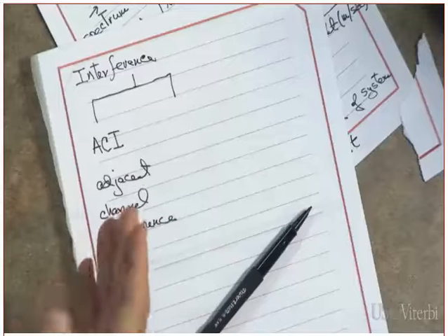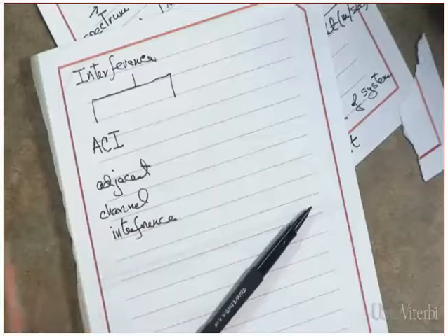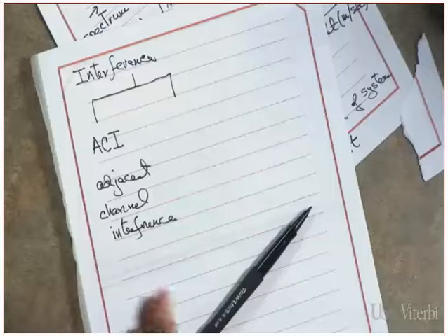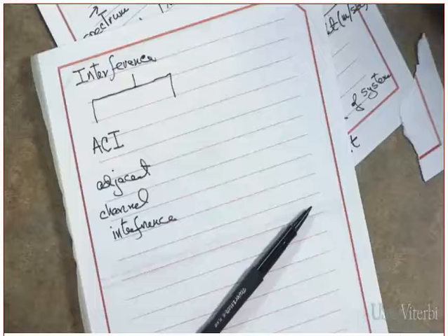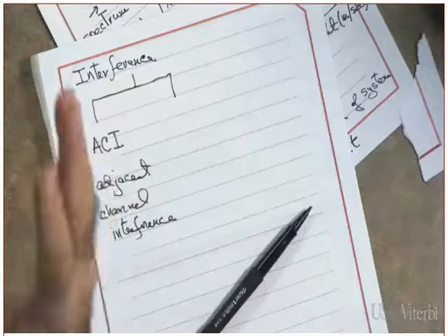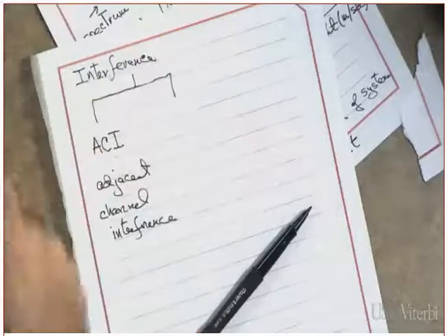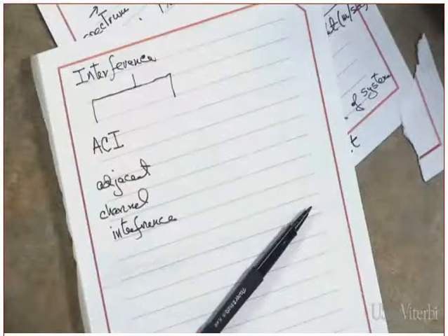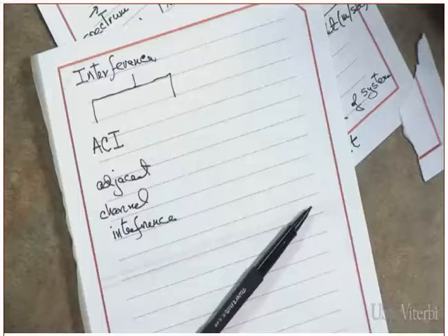Now you do understand that one of the most important parts of designing an RF transmitter is to make sure that your emission, your spectral emission as a transmitter, needs to be confined within the channel that was allocated to you. You don't want to spill into other channels, because you are going to cause interference into them.